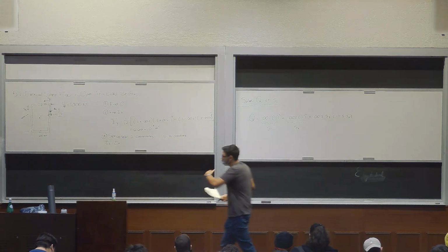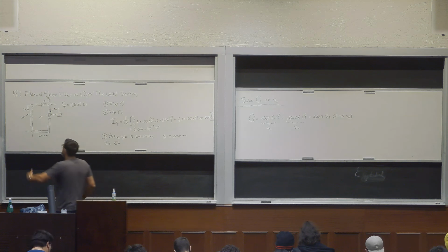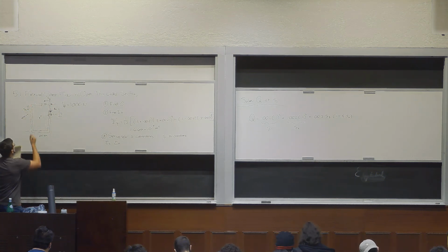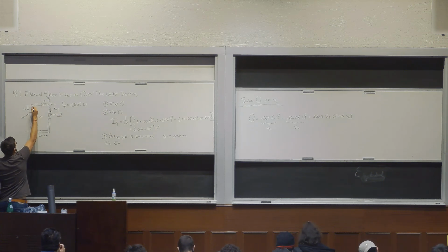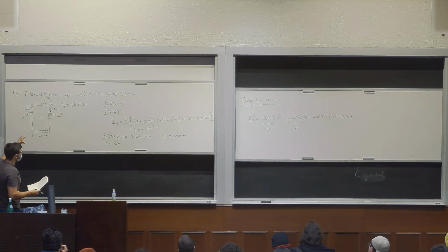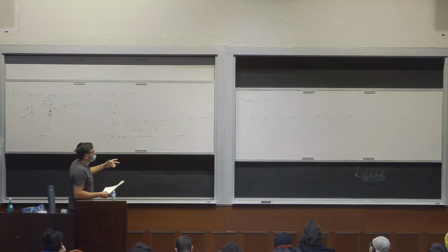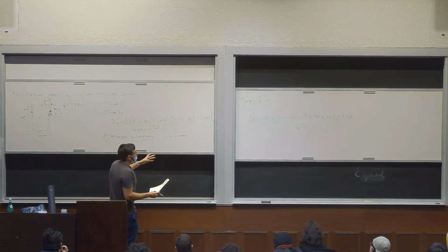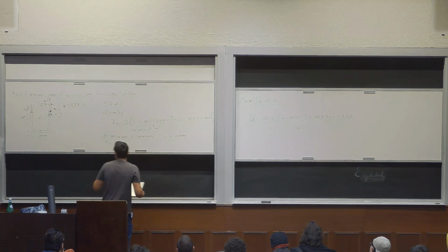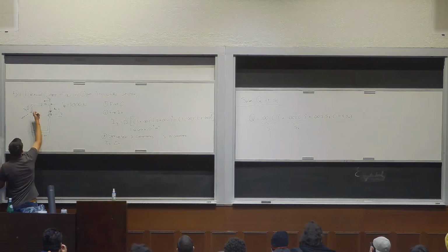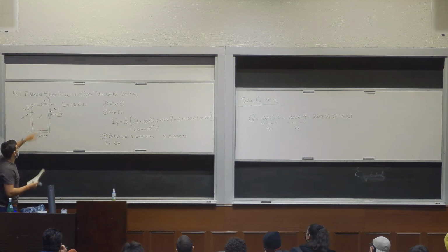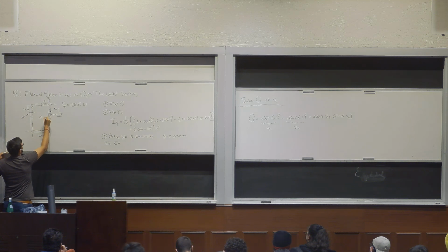All right, so this is a constant addition process. You go to the maximum here, maximum there, and then we make a cut here, for example. You have this area, so the area is going to be that S3 times the thickness. And then times the position of the centroid, which in this case would be half of whatever S3 is, but we're defining it from the original coordinate system.